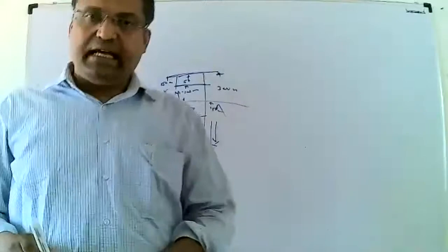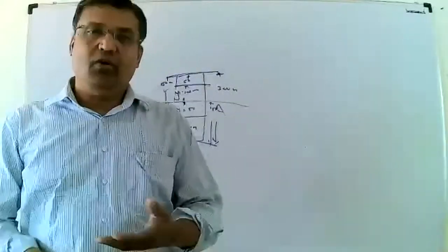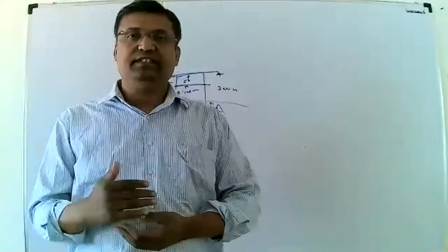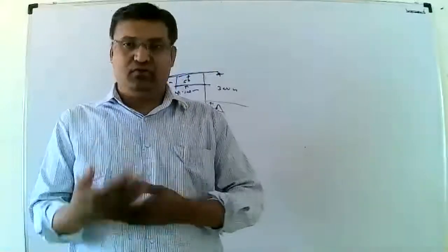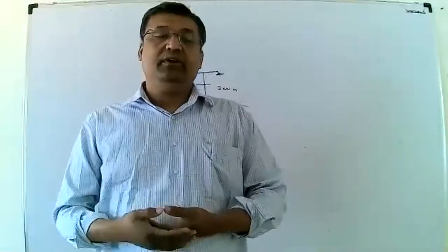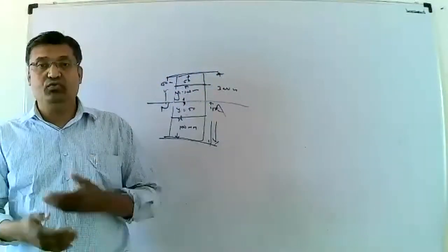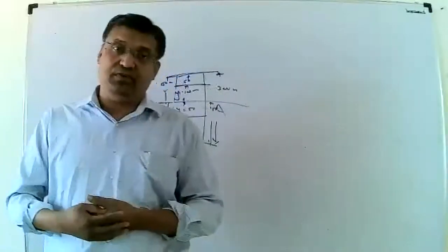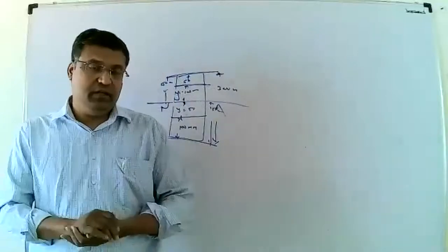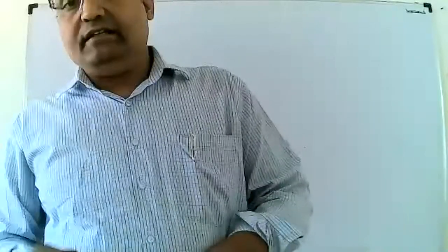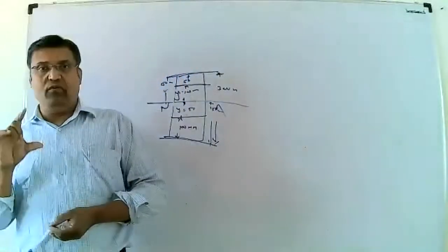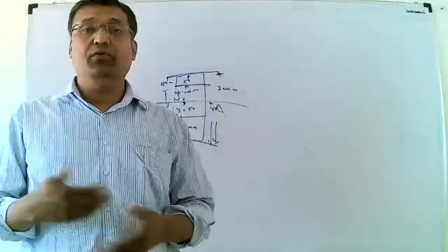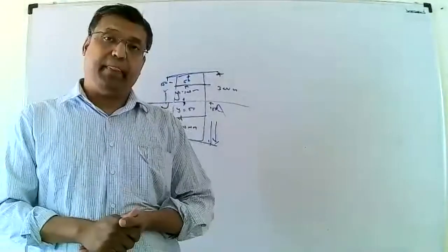Once we understand y, in some examples the distance is provided above the neutral layer or below the neutral layer, but we have to understand how to measure distance y from the neutral axis, below or above it. That is very important. Once we find the distance y, you can easily calculate shear stress at any distance above the neutral axis or below the neutral axis.